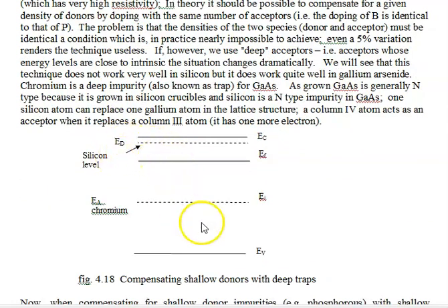Here we have, for example, I guess I call it the silicon. It could be anything. And we have the electronic state for silicon, which is about 40 or 50 milli electron volts below the conduction band. And instead of using acceptors, which are shallow down here, we use deep acceptors, which basically have their E_A, their acceptor level, right at the intrinsic, right in the mid gap.